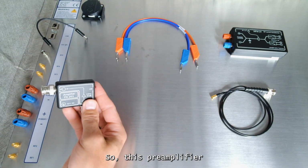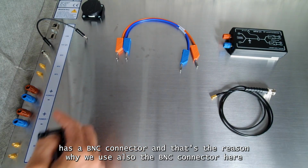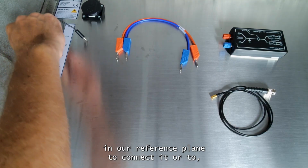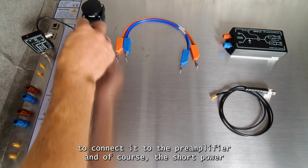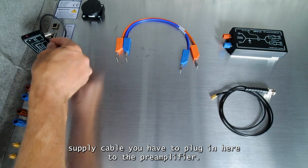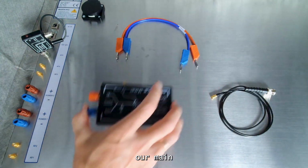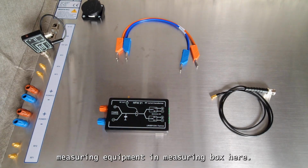So this preamplifier has a BNC connector, and that's the reason why we also use the BNC connector here in our reference plane to connect it to the preamplifier. And of course this short power supply cable you have to plug in here to the preamplifier. So the next step will be our main measuring equipment, the main measuring box here.